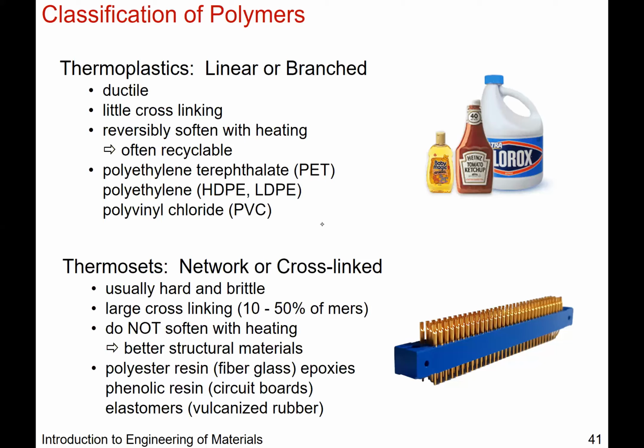Now, the last example, elastomers, vulcanized rubber, we talked about how these chains can actually be cross-linked with sulfur, and that's basically what has made Akron, Ohio, the hotbed of the polymer industry, right? It's because of Goodyear, and Goodyear figured out that you can expose polymers to sulfur, and if you cross-link with sulfur as opposed to carbon, you can vulcanize these materials and strengthen the properties that way.